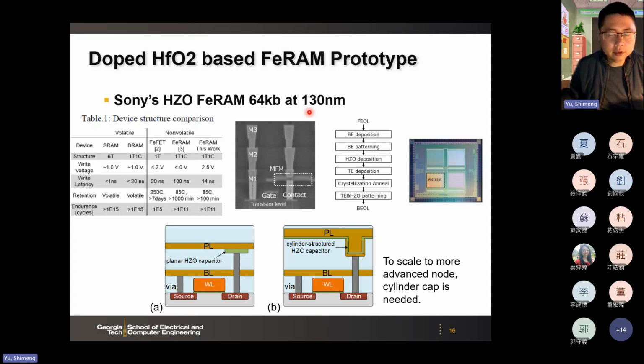Micron is a memory vendor, and they changed their DRAM process so that in the 1T1C, the C becomes ferroelectric. Micron also demonstrated a two-layer 3D stackable design. For their 1T1C, the T, I believe they use polysilicon, so they can do it at the top of the interconnect.